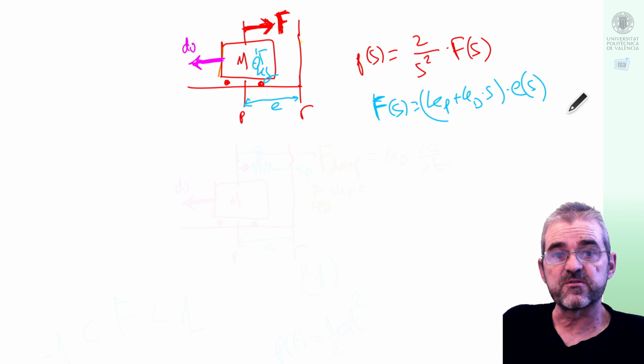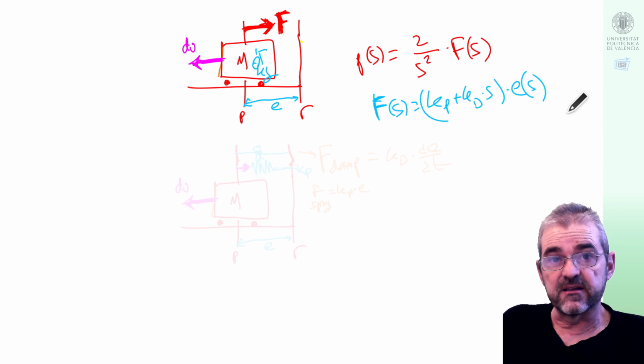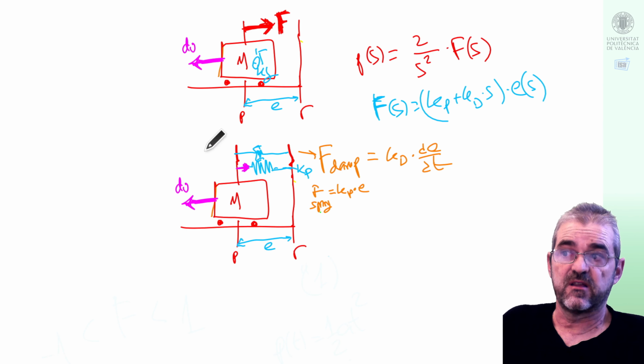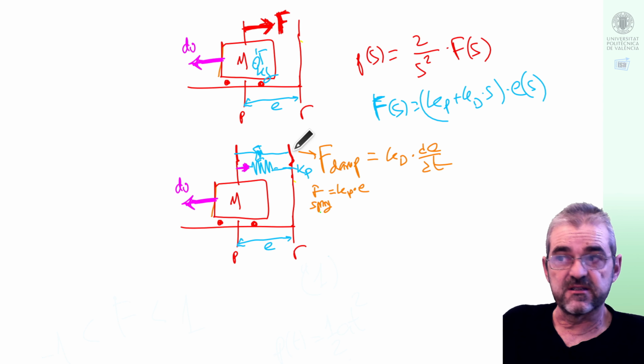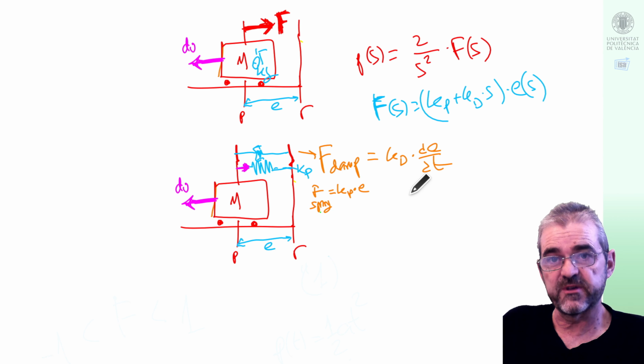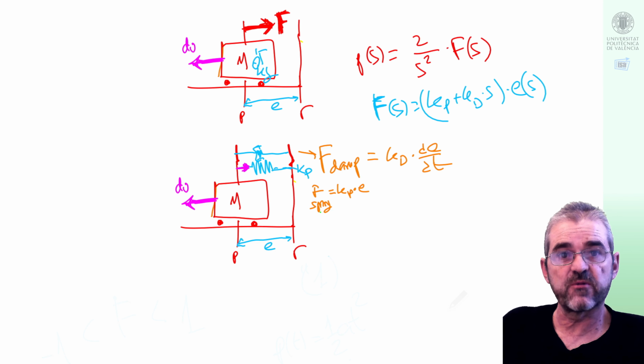And in previous videos, we thought that this proportional derivative controller had a mechanical analogy in the sense that a force proportional to a distance is a spring and a force proportional to a velocity is a damper. But of course, in most cases, controllers are implemented via some sensing and actuating technology and control software. So we have the flexibility to change the constant just by typing on a keyboard. But well, the mechanical analogy helps us understanding what we are doing. Good, so this is our system.